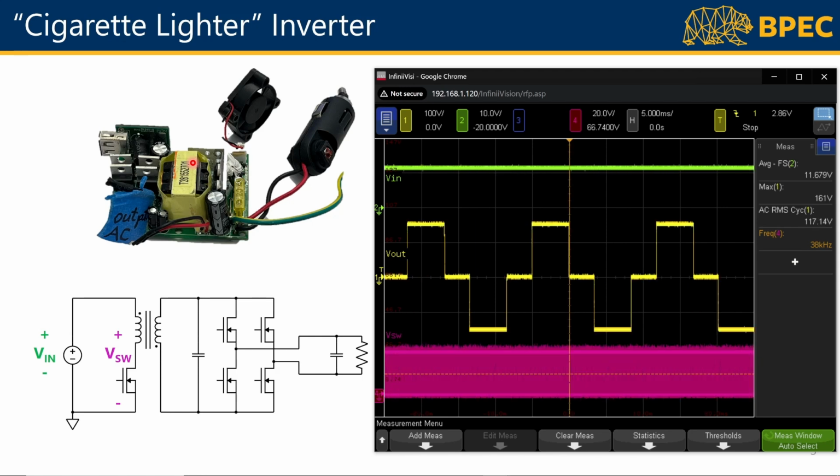All right, now we can zoom back out and try to understand what's going on with this yellow output voltage. I said that this inverter is meant to emulate the grid, so we'd expect a 120 volt RMS sine wave output. But in fact, this is a very cheap inverter, and so instead of including the necessary filtering components to provide that sine wave output, they omit those. They just take the output of the unfolder and leave that as a 3-level square wave.